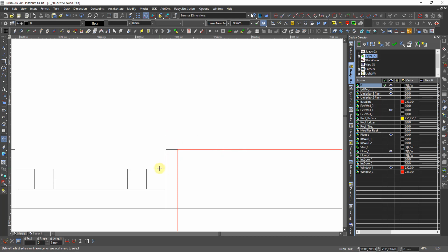If I use a 1.5 inch stud in between, that is 36 from V. Oh, why I don't get this? V, and then that piece of wood is 36, but there's also 15 millimeter gap on each side of the window. That's 30, so 36 plus 30 is 66.